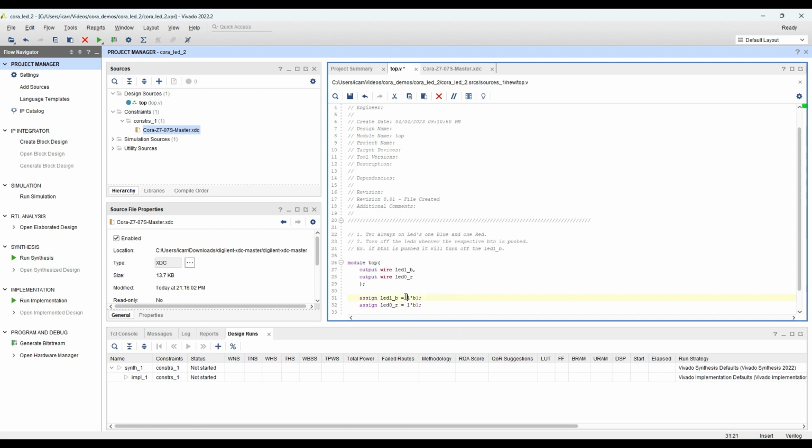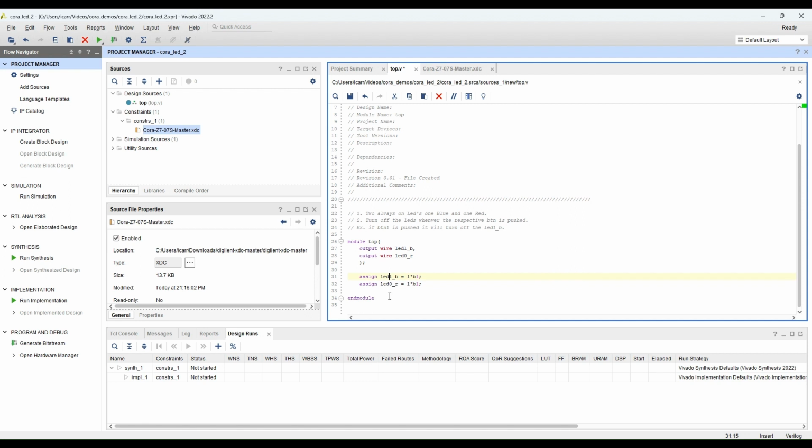So this syntax pretty much just says this is a binary string with length 1, and that's being assigned to this wire. And so whenever we use a wire, it has to use this assigned variable. And the reason why we're using wire is because later on in the next videos, we're going to want to be able to transfer this variable through different modules, and that can only be done with a wire and not a register.